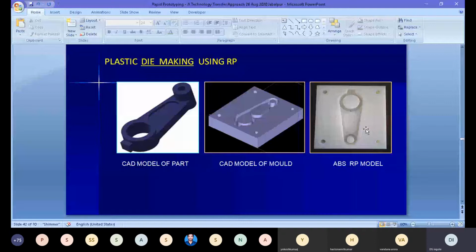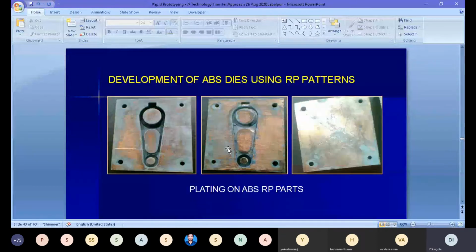to fabricate the wax patterns, again, since it is manufactured layer by layer and there are the stair stepping effects, and then the liquid can get entrapped in this, some metal deposition was performed. But this metal deposition, that is metallizing of plastic parts, is quite not possible in these 3D printed parts